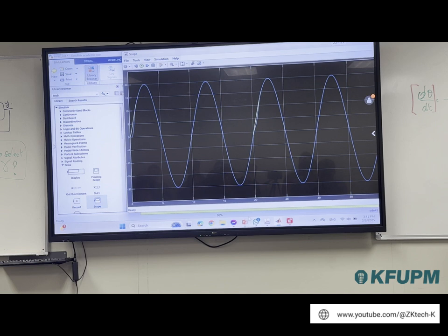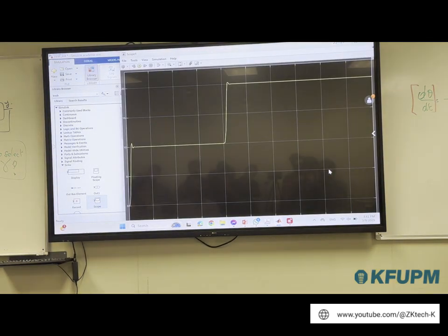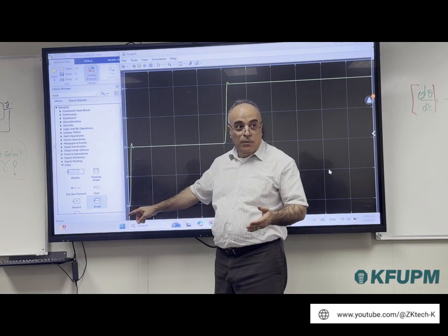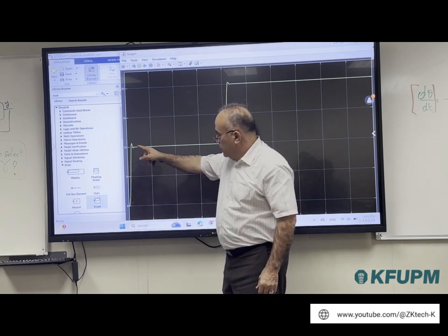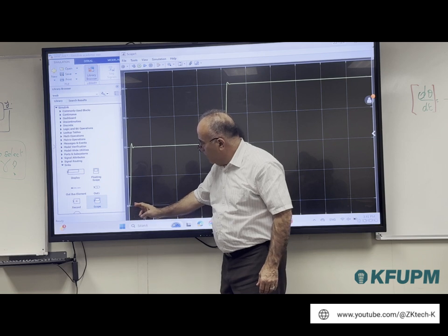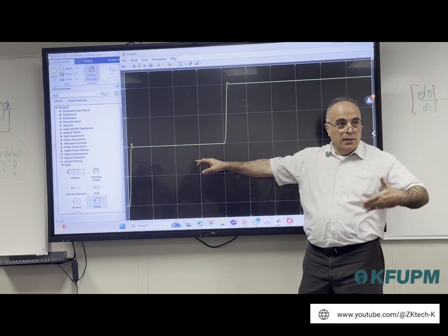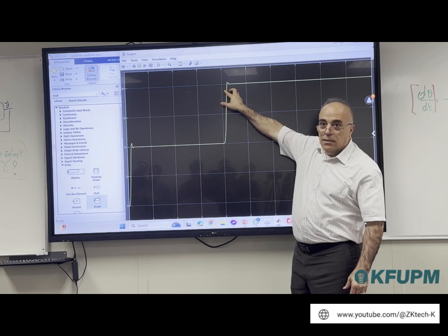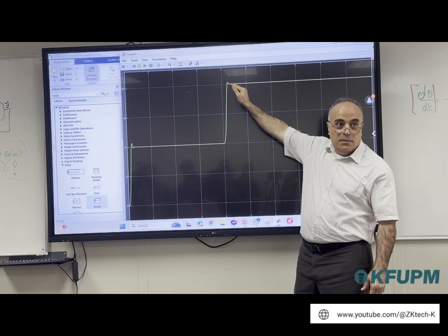And then if you look at the speed at which theta was able to correct itself, see, this is theta. It was 0.01, so I made it 100 times faster. So it gives me a very quick response. It converges in maybe 0.1 second. And theta here is constant. So the controller was able to reach the reference. And then I made the jump and it reaches in maybe another 0.1 second. And then the controller was able to reach again and correct. Everybody's okay with this? Yes, sir.